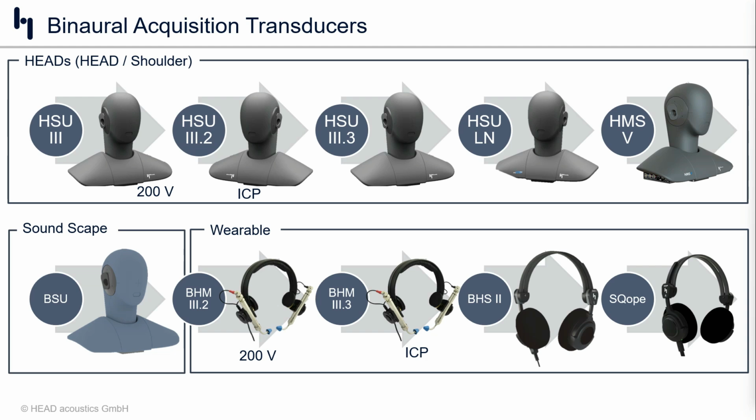You have the head look at it, you then measure the response of the head and then invert that response in the equalizer, and you then have a flat response where all you need to do is calibrate the microphones, and you have a measuring microphone for a free field incidence situation.